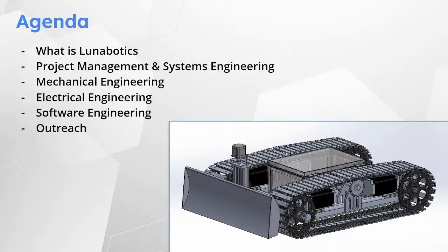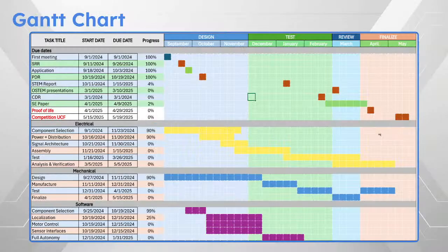Right. As far as safety, I would say our standard operating procedure is going to be making sure the robot is off before you go touching anything. That's a big safety concern. There's a lot of pinch points on this robot. It being a track driven robot, pinch points are a real concern. So the main rule is never work on the robot without the kill switch disengaged, engaged, however you want to describe it. There should be no power going to the motors whenever you're touching the robot. End of story.